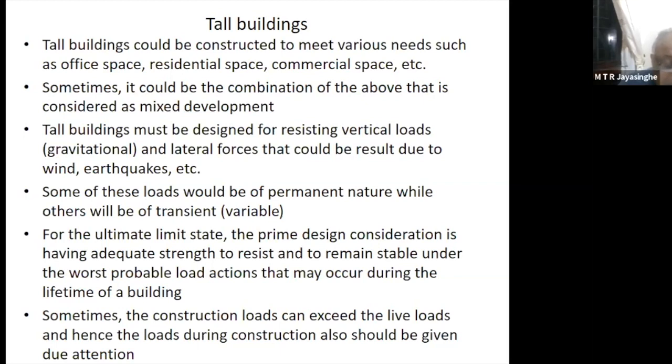And if you look at the live load scenario, unless you go for storage, it's very hard to find enough furniture or people having sufficient weight to cause the kind of imposed loads that you have assumed in your structural design. So because of that reason, always keep in mind, slabs are very safe. The only critical location in a slab is the short span. So if you want to be generous, only there.